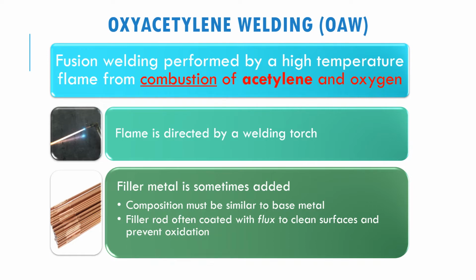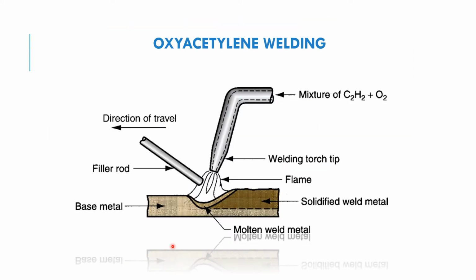The composition of the filler must be similar to the base metal, and the filler rod is also often coated with flux to clean the surface and also to prevent oxidation. Now let us see the schematic diagram for the oxyacetylene welding.